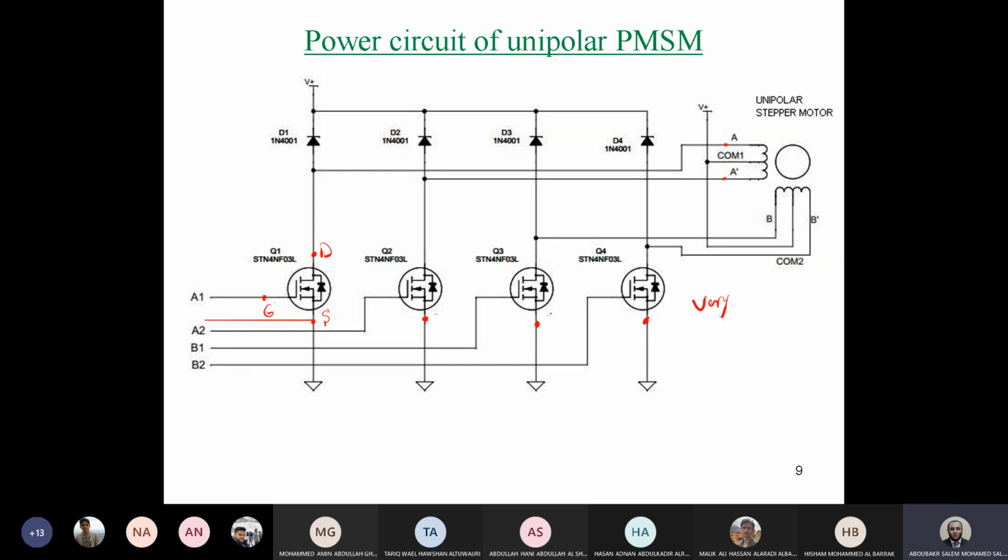This is all you may need in order to draw the current from a power supply, not from the microcontroller for sure, because you cannot draw high current from a microcontroller. This is regarding the gate current. Okay, and you can make a very simple circuit like that, just a transistor with a resistance like that, and this is a VCC, which will be the supply of the gate, and just take the output here to the gate of the transistor. And this can be connected to your microcontroller.